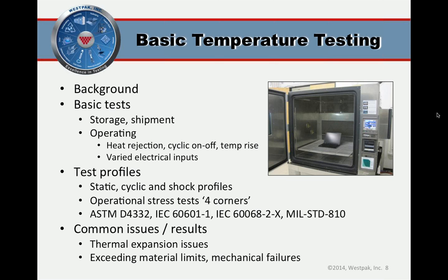For all these stress tests, there's a concept called a 4-corner test. So let's take our temperature and voltage example. We would test high and low temperature and high or low voltage input into the unit and make sure it operates in all 4 of those conditions. And the idea here is that if it can operate at those 4 extremes, all the area contained within that box, it should do fine in. That concept applies to most of the tests we'll discuss today.